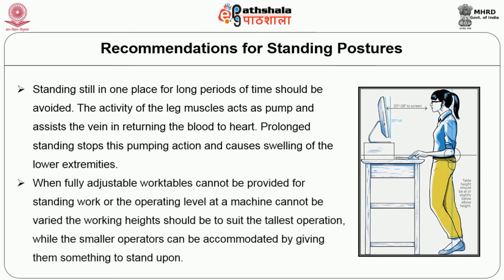When fully adjustable work tables cannot be provided for standing work, or the operating level at which the machine cannot be kept in the varied working height, it should be provided to suit the tallest operator, while the smaller operators can be accommodated by giving them something to stand upon.